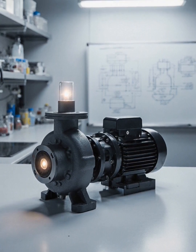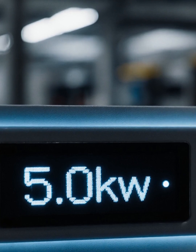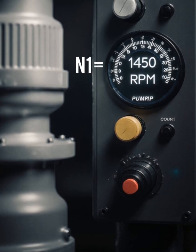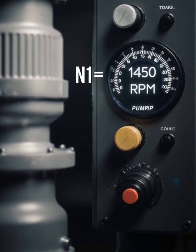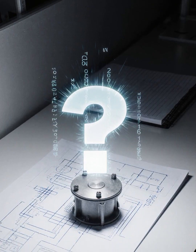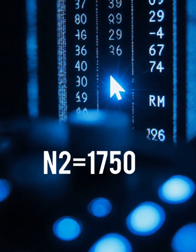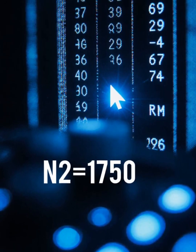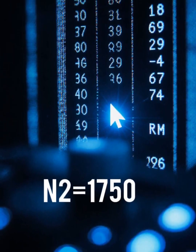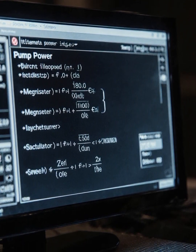Consider a pump operating under specific conditions as a numerical example. Initially, the pump requires 5 kilowatts of power. This power consumption occurs at a rotational speed of 1,450 revolutions per minute. The objective is to determine the power consumed when the speed changes. Specifically, we need to calculate power consumption if the speed increases to 1,750 revolutions per minute. This calculation will demonstrate how power demand changes with increased pump speed.